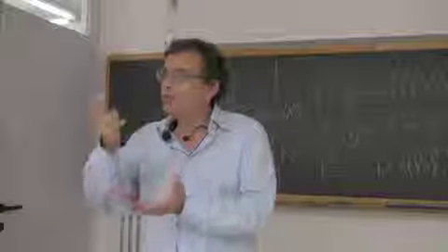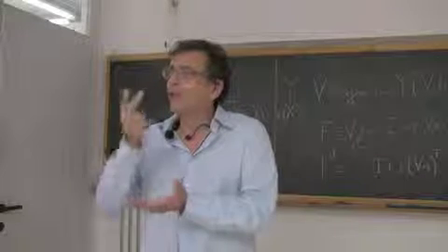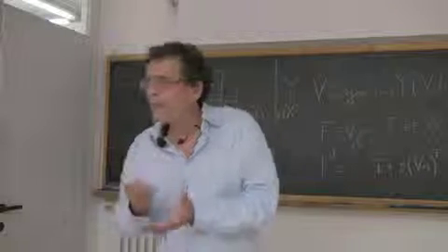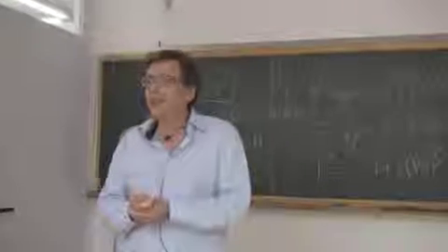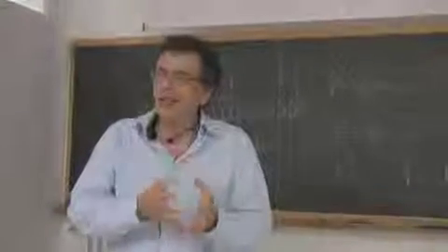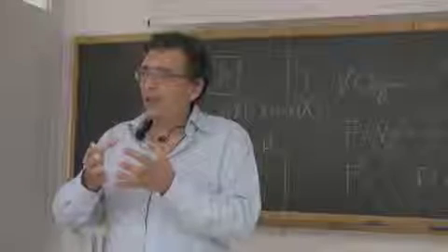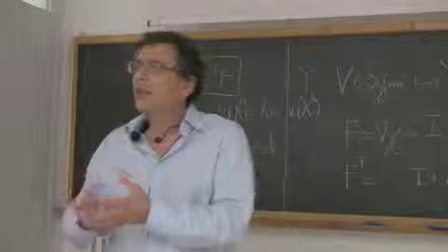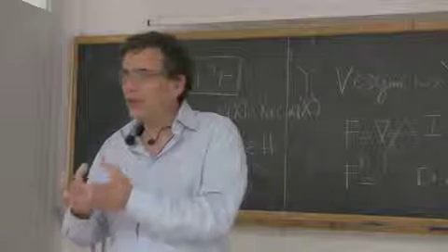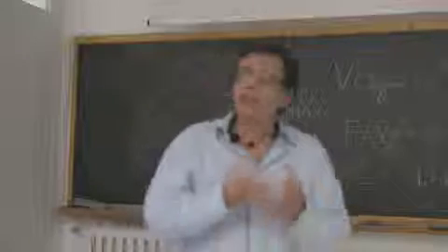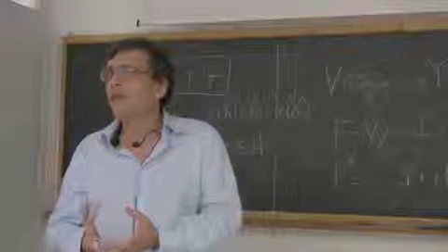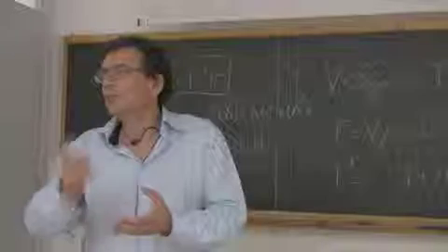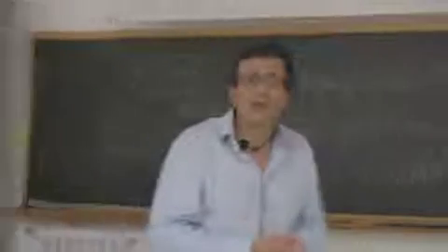Only 2 coefficients are needed for every isotropic tensor function. So if you want to study linear elasticity of isotropic solids, you need 2 Lamé coefficients. If you want to study the viscous flow of a Stokes-Navier fluid, you need to introduce 2 Stokes-Navier coefficients.